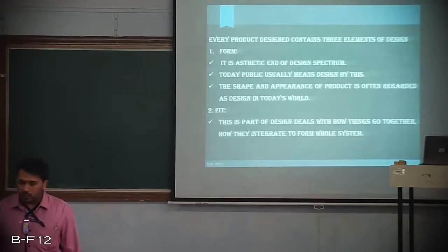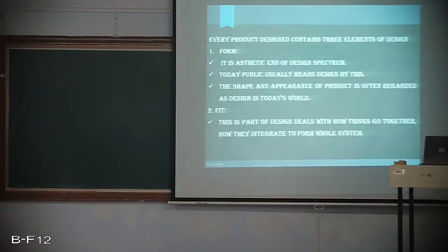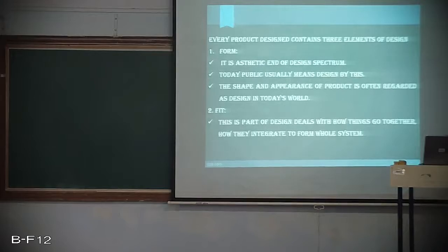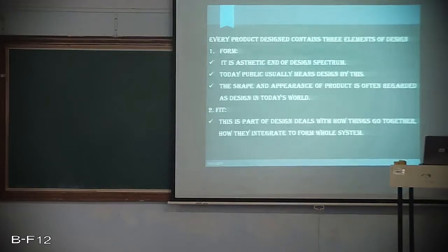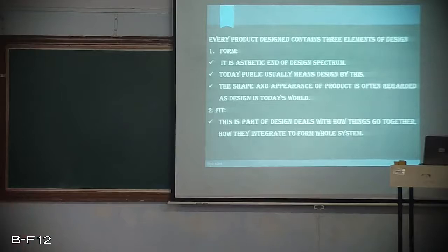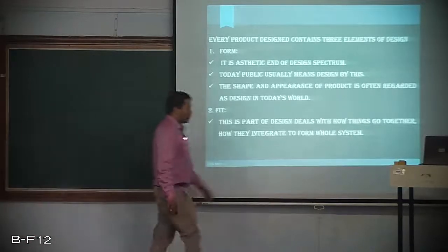And even if the parts are fitted together to form the sub-assemblies, if those sub-assemblies do not fit with respect to each other to form the assembly or product, then it is not possible for us to achieve the product, because the sub-assemblies are not fitting. Hence, we need to always make sure that there exists a perfect fit between the parts which make the sub-assemblies and also between the sub-assemblies which make the product. That means the parts must be manufactured by using interchangeability and selective assembly processes.